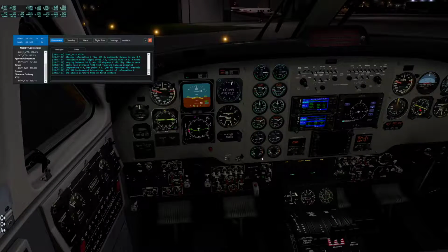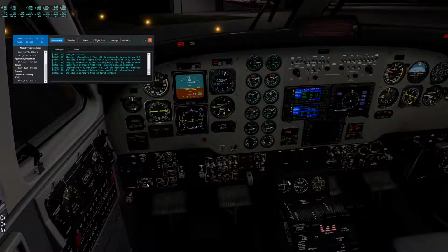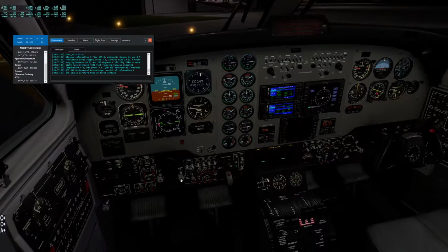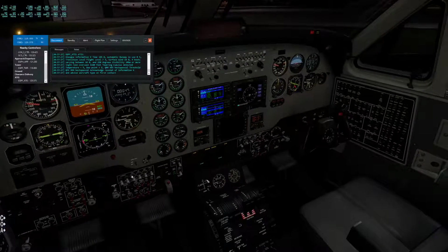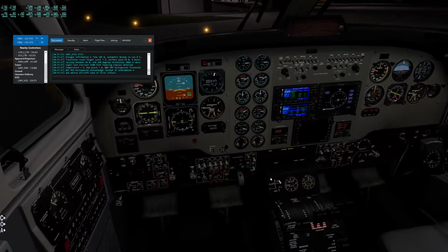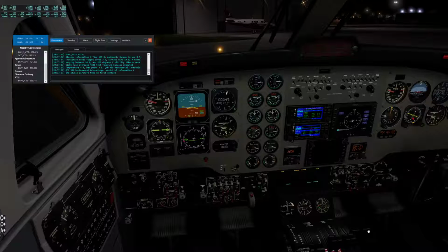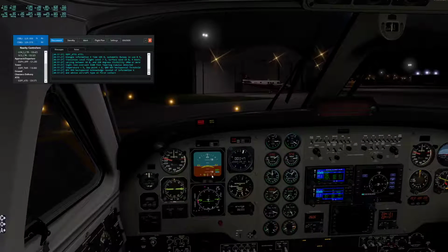What am I going to do next? Going for a right engine start. Checking the prop is clear. Start to engage. Wait for about 15% on the turbine, engage. Introduce fuel. Make sure the ITT doesn't go into the red line. Turn off the ignition, turn on the generator. Check that the ammeter is showing some load from the generator.